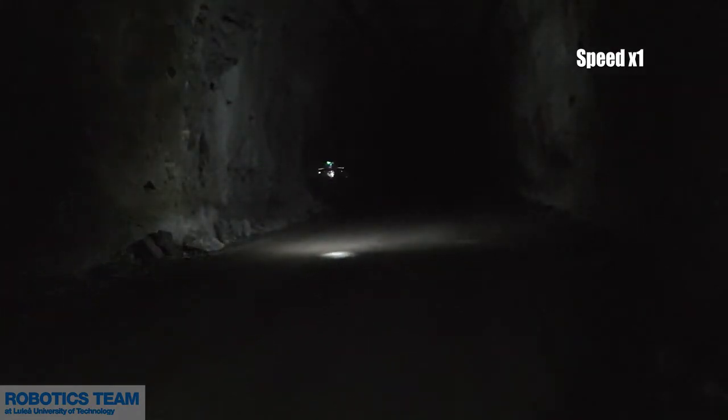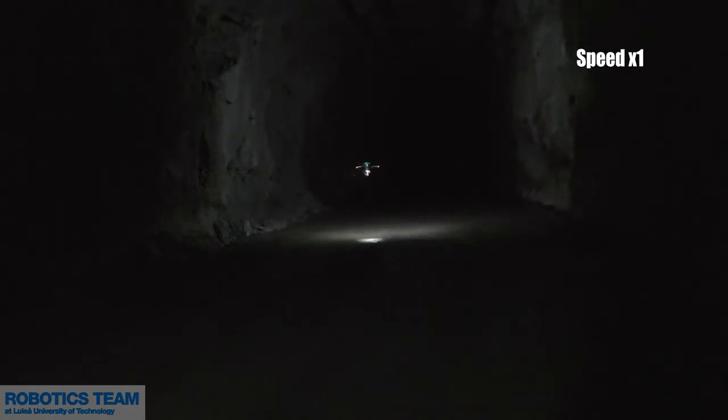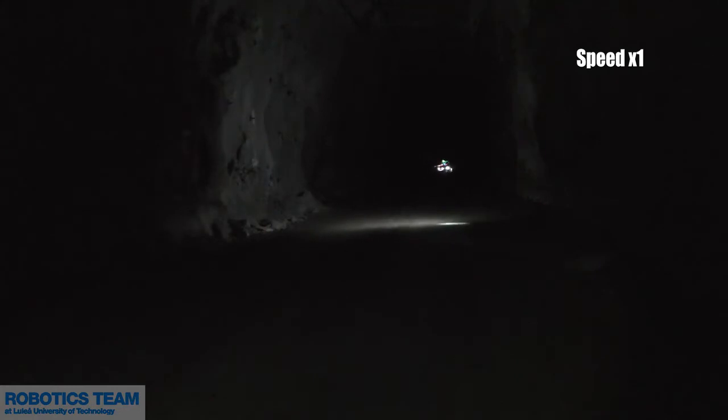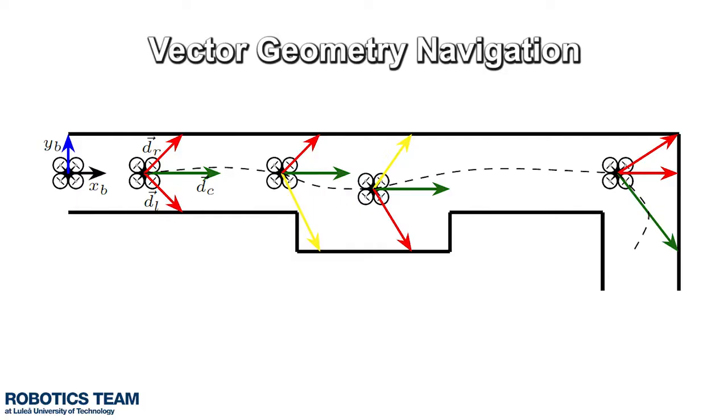While 3D LiDAR solutions for pose estimation would increase the cost of the platform, we present an architecture that considers the flying platform as a floating object moving along the tunnel, removing dependency on accurate position state estimation. To successfully navigate in a tunnel, the challenge for the MAV is to identify the direction of the flight in unknown areas, while avoiding collisions to the surrounding walls.